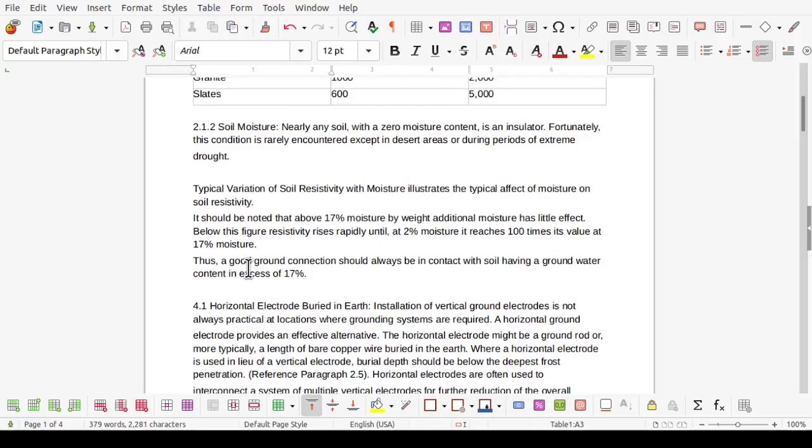You might as well go for horizontal antennas or build massive radial systems, because pounding any number of ground rods is not going to bring you much relief, unless that mountain you live on is a lot of cracked limestone and percolates well. I discussed that the last time.